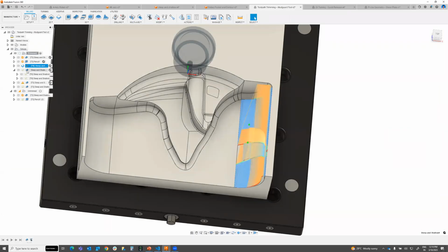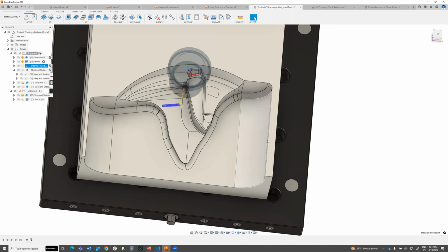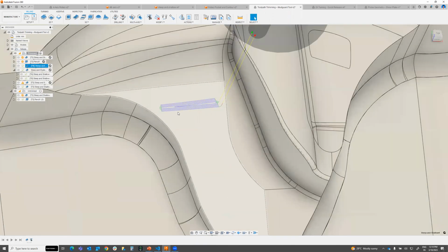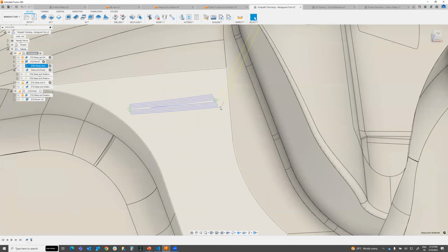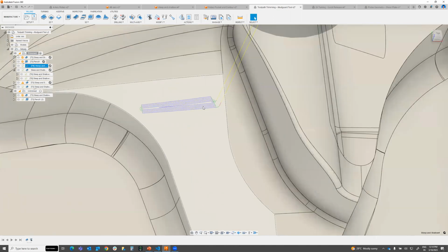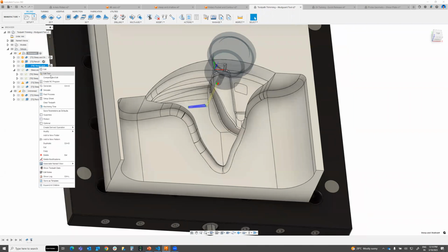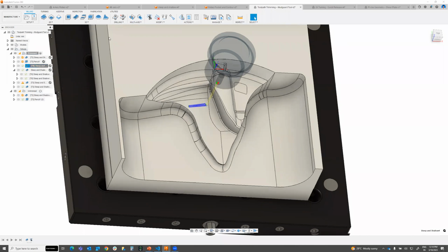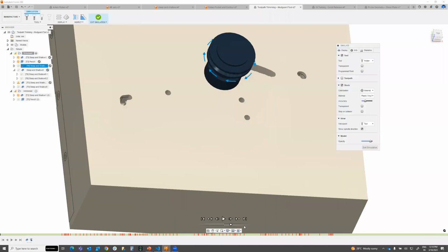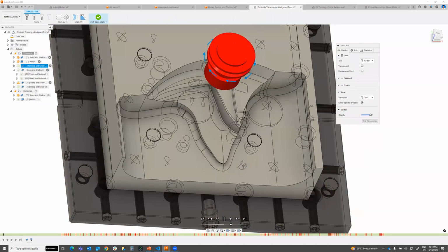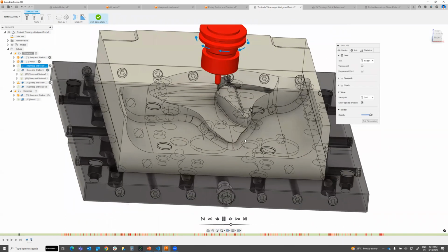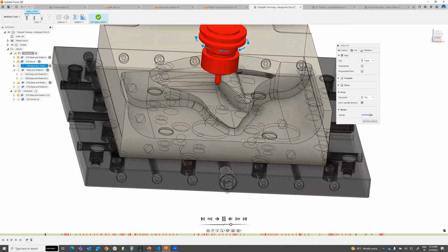This helps you, and you can see now my toolpath was saved only the inner of this profile. What are the options I have used? It is trimmed outside and it is left out. I will keep both, then it will give you both options, and you can run this toolpath as you require to machine it. Switch up the stock and you can see now, it is machining only for that particular area.